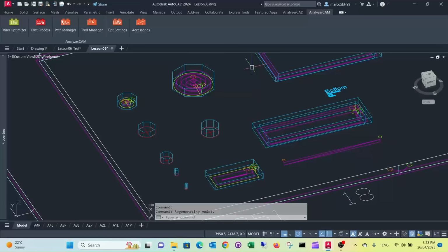Your CNC machine usually ends up with a small bit when it does just a cutout, and that gets sucked up to your dust extraction, which is not very desirable. So what you can adjust in the questionnaire is from which diameter on you want it pocketed or just cut out.